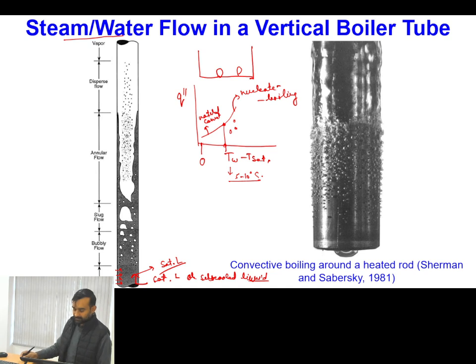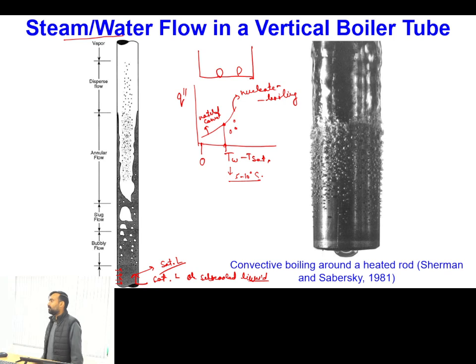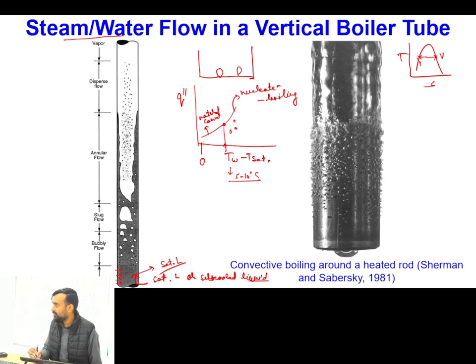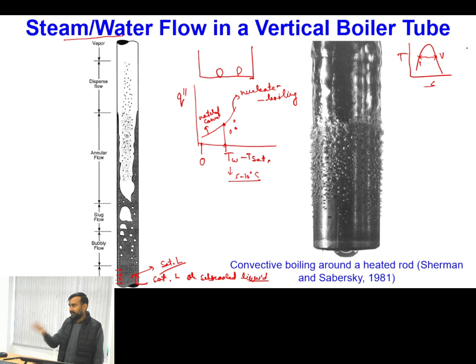What is the reason why? See, in thermodynamics what do we study? In thermodynamics we study that if this is my TS diagram, and this is the saturated liquid state, if I add heat, the liquid will start getting converted into vapor, and at constant temperature I will get vapors forming until the entire liquid has converted into vapor. Then the temperature remains constant.